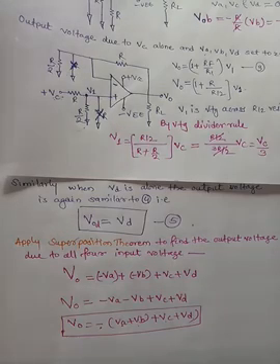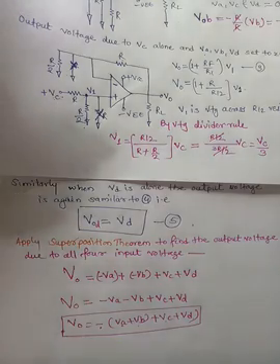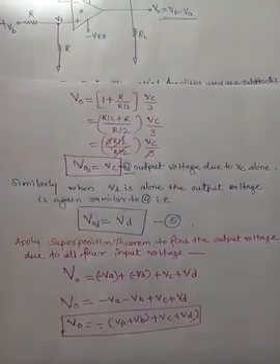The gain of this summing amplifier is 1, as we have set all the resistor values equal to R, and therefore the scale factor that we have selected here is equal to 1. Any scale factor can be used for the inputs by selecting the proper external resistors. In this case we have selected a scale factor equal to 1. As the output is the summation of the inputs given to both input terminals, the circuit is called the summing amplifier using a differential amplifier. In this way we have designed a summing amplifier with a differential amplifier. Thank you.